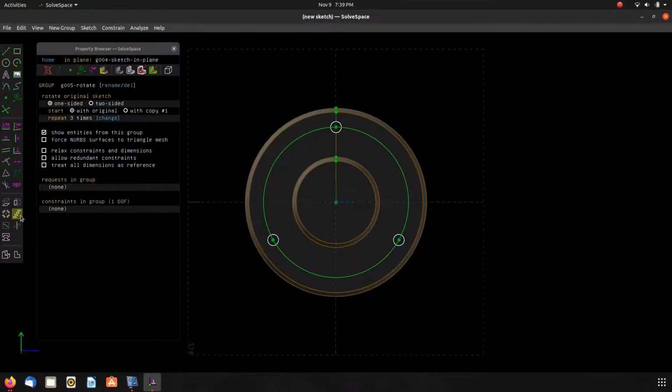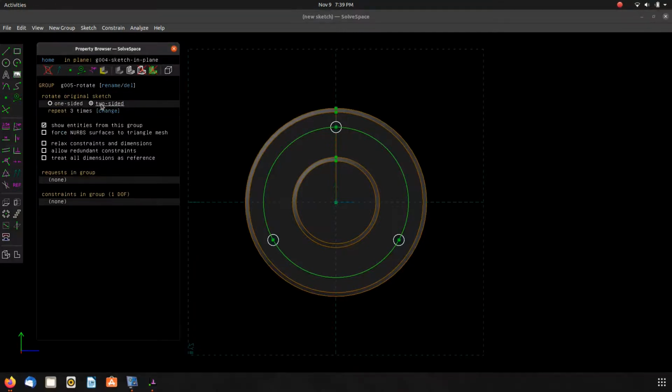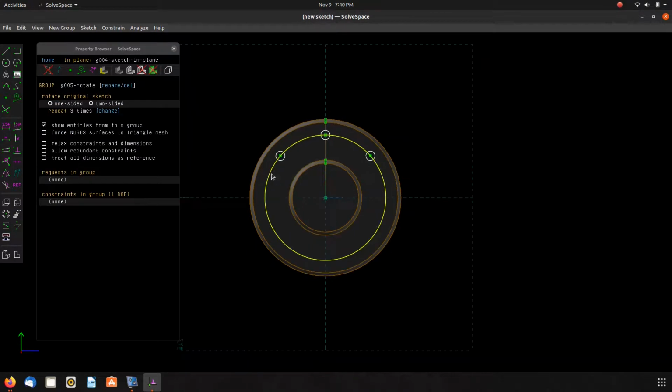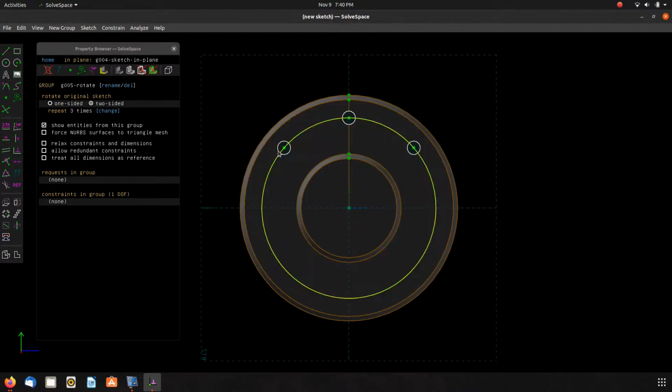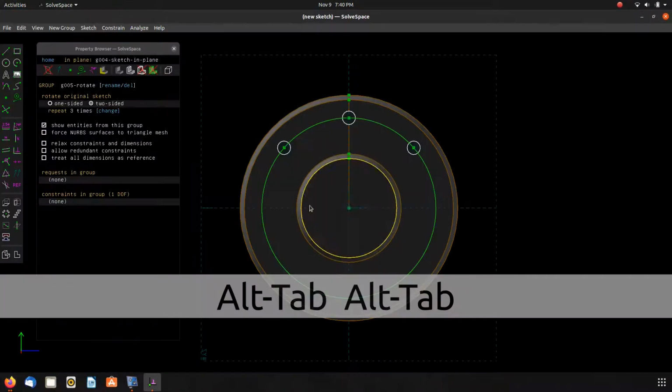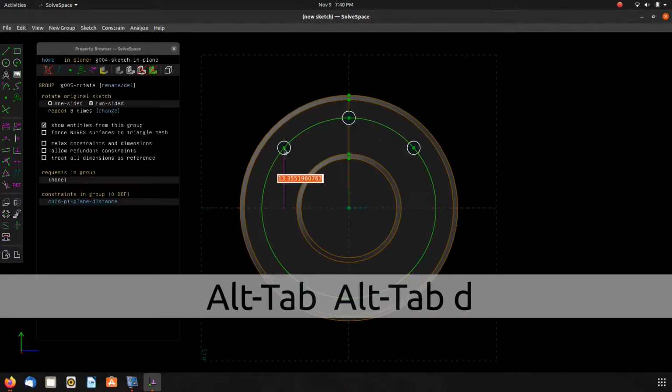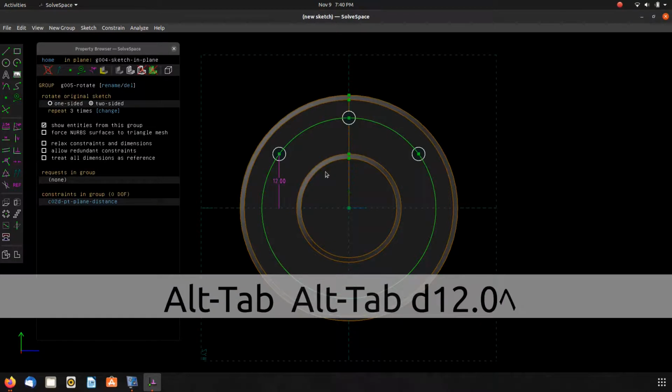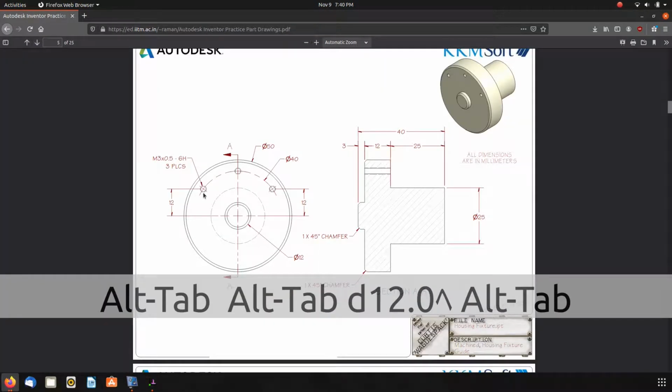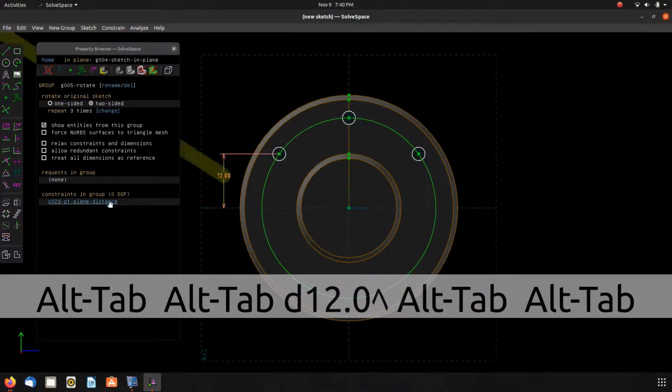It's a 3 millimeter shank. So what you would need to do is look up a tap chart, and then you could go from there. I don't normally work with metric, so I'm not sure what a normal minor diameter for 3 millimeter threads would be, but again, it doesn't particularly matter, so we'll ignore that.